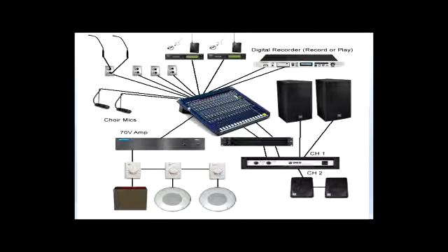And those mics are supposed to be powered. In order for that microphone to work, it has to receive power through its connected cable, because it has some electronic circuitry to operate that mic, and that is called phantom power. So when you see a button on the mixing boards, in different spots, it's going to say phantom or phantom power. It's 48 volts DC, usually. 48 volts DC is being sent to that microphone.